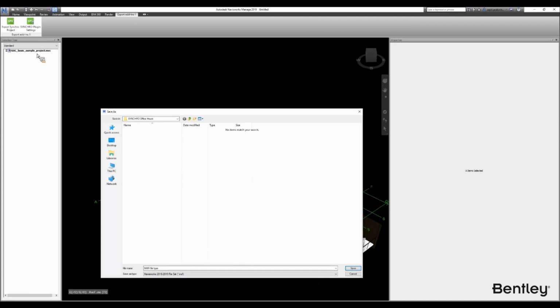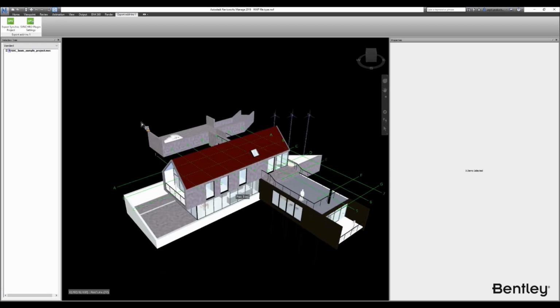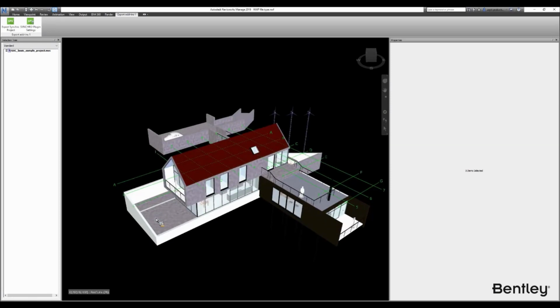All the models which are appended into the project are referenced to it. So when you update a model, the link remains the same. All these SYNCHRO IDs are saved in the local NWF file set. With the NWD, those files are not referenced to the original model at all. Every time you create an NWD, that's a separate entity itself. So you want to make sure we save this as an NWF, and we keep using the same NWF file for every future update. So I'm going to save this one as NWF file type. After every export, you want to make sure you save it.